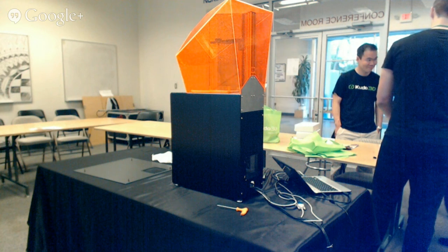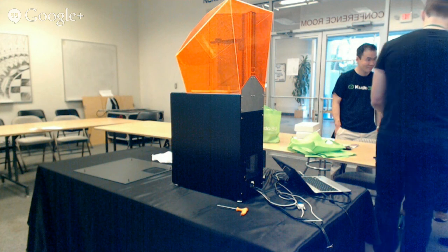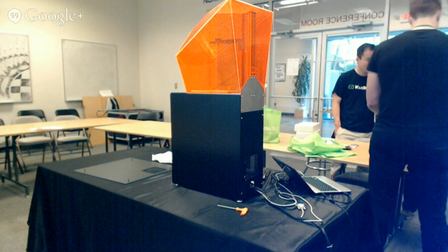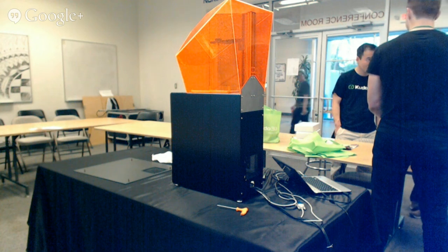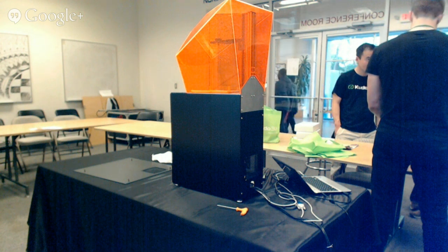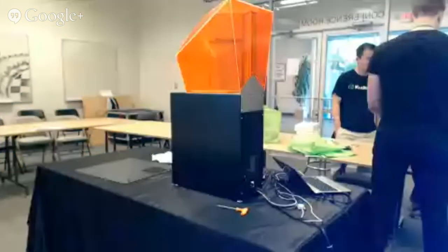And that's where you see the first one were better, but this was the last one, and it was moving so much, the metal, that as I moved the part in, it was leaving these gouges. It was going way deeper than I intended. And this is a trouble because I can only take off so much metal before bad things happen. So I had to stop because the deflection was too great. Mainly this edge here is too sharp. But that's mainly because I've messed up.